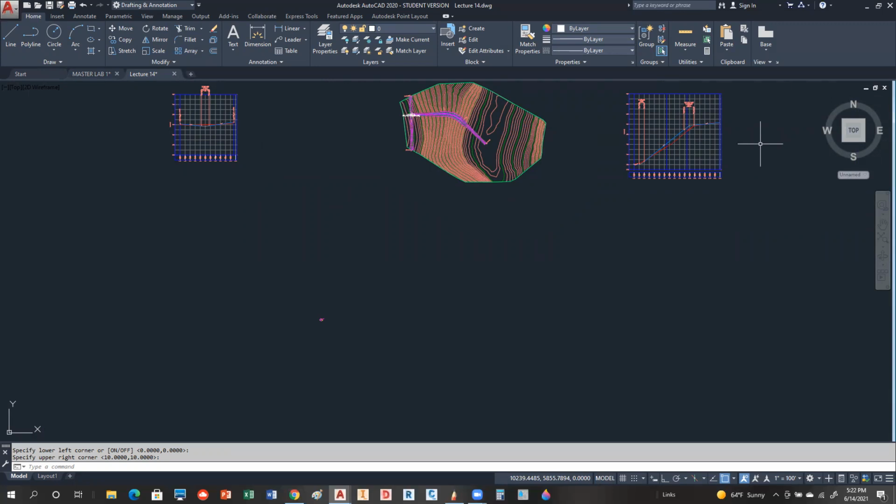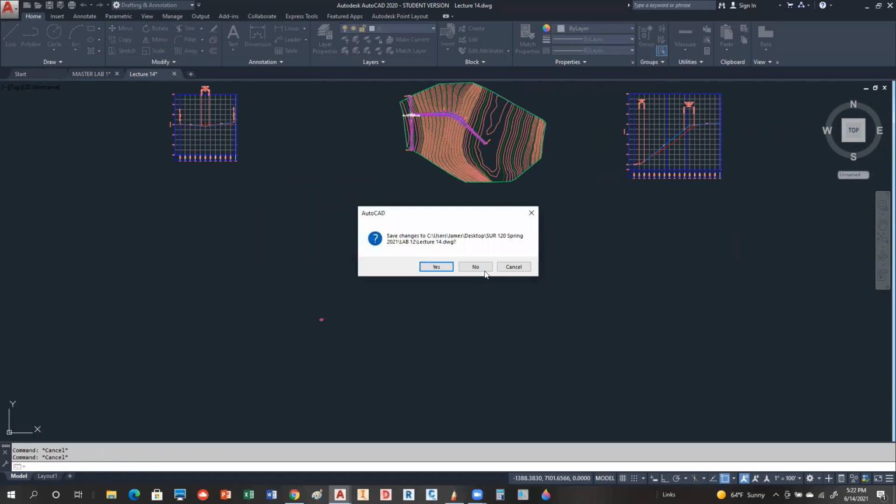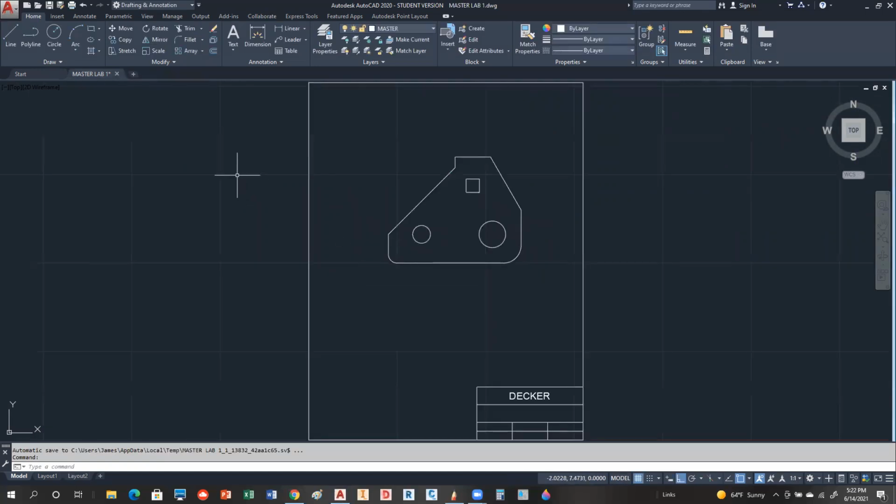So if you have a choice between the two zooms, usually what I'll do is a zoom extents, because that's going to typically give me the biggest picture that I can get. And again, all I'm doing is just typing in Z enter, E enter, or Z enter, A enter, okay? So that's really cool. You can just do that very simply by typing.